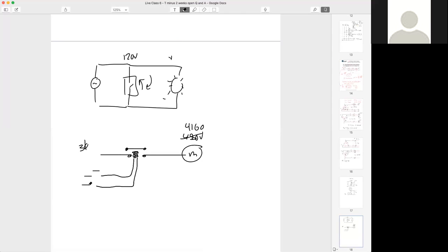to control it. So let's look at this. This is 120 volts, no different than flipping a light switch. And this is a push button station. An operator or a technician can push this button closed. It'll energize this coil. It makes an electromagnet that attracts these contacts, closes that switch, and puts our 3-phase power to our motor, and our motor starts.